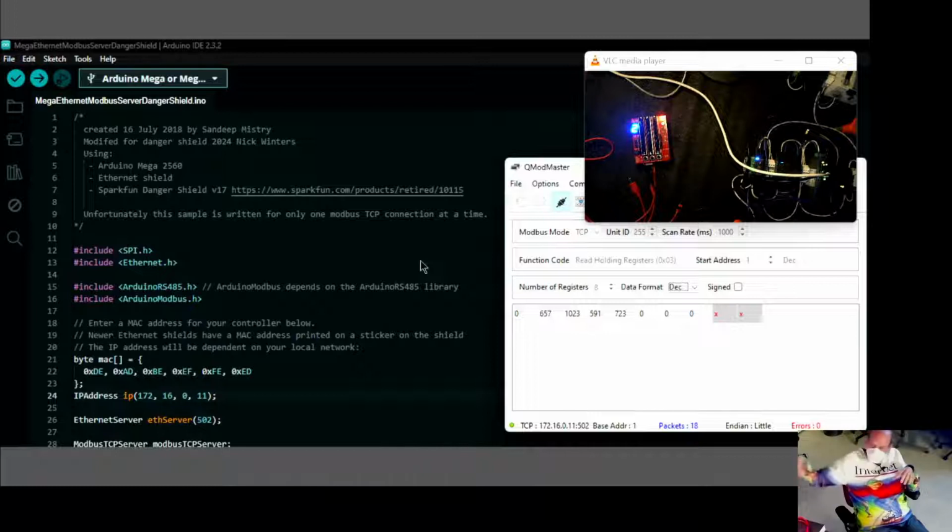I tend to have an isolated thing, which is why I chose 172 whatever, because it tends to not be the address of the rest of the network I'm dealing with. So when I have my laptop, it's not unsure about where is my PLC, which network is it on, whereas if my PLC and my local network are 192.168, it might.